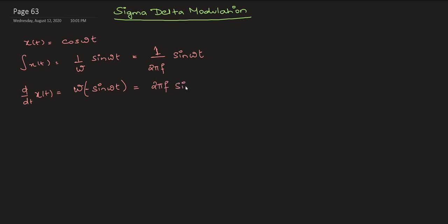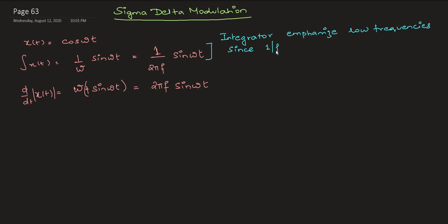So you see that the low pass filter has a role in delta modulation, and a low pass filter is a filter which works with the low frequencies. Now what we do in sigma delta modulation is bring in an integrator, which is our sigma. Sigma stands for the integrator because the integral in continuous time is equal to sigma in discrete time. That is sigma delta modulation at a very broad level. We are not going into the depth of it.